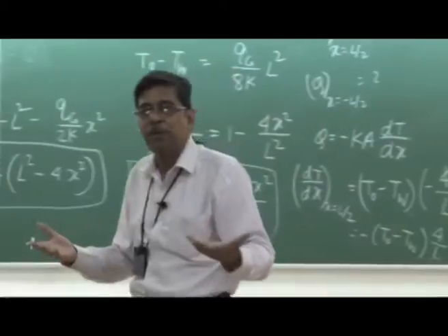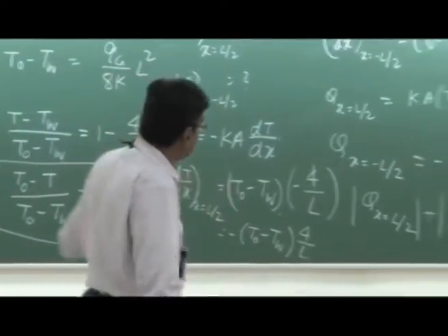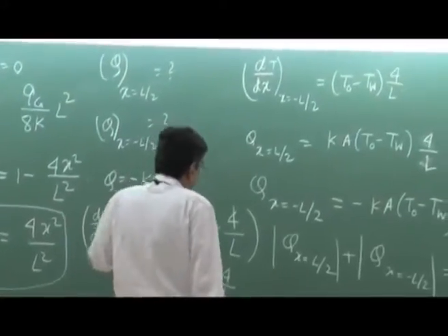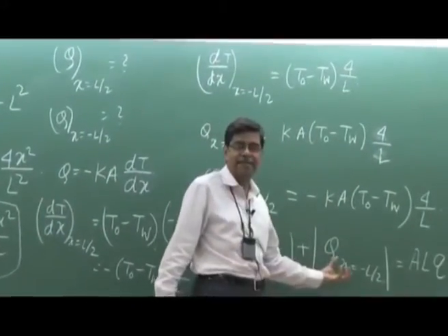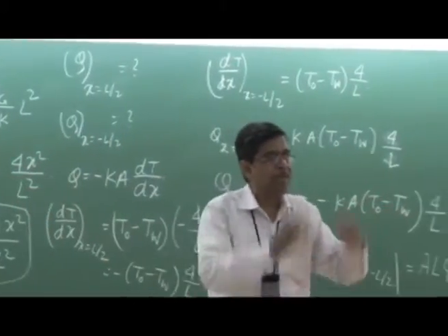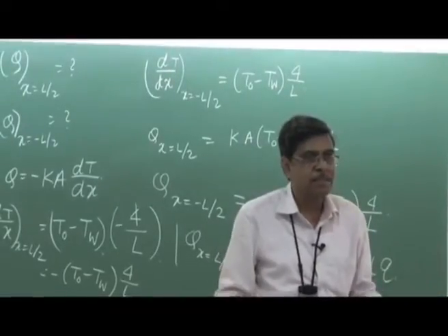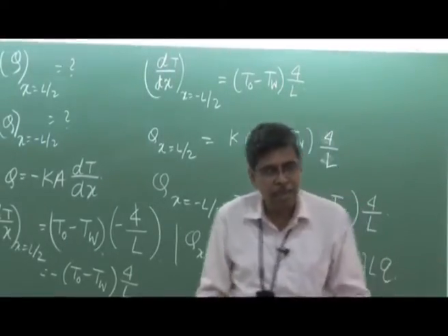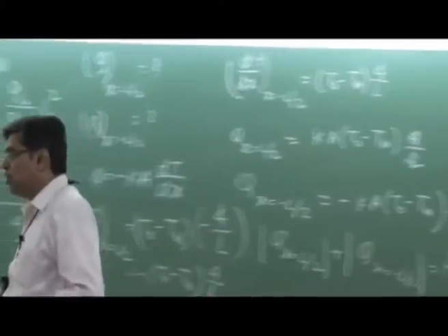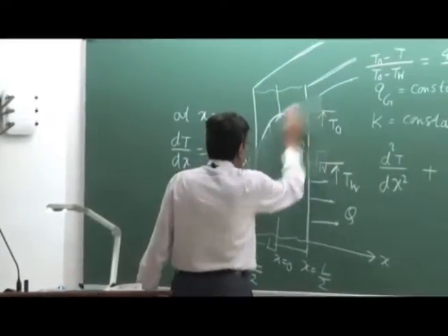You may ask why are you doing this, sir? But still, for satisfaction, we have used the differential equation point to point. Why not make a gross balance as a whole, that the heat flowing out from the two surfaces equals the energy generation, which means the steady state concept persists. That means there is no energy accumulation within the system. So this is a very simple, classical example of heat generation.